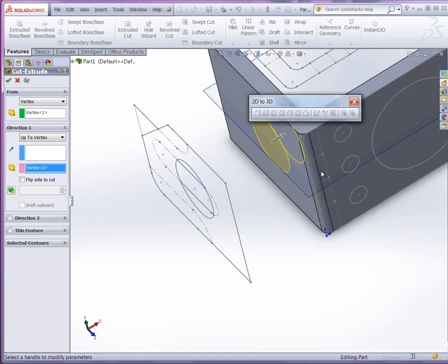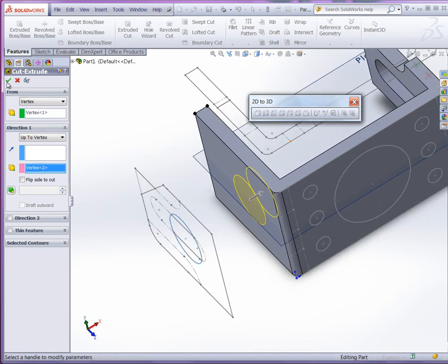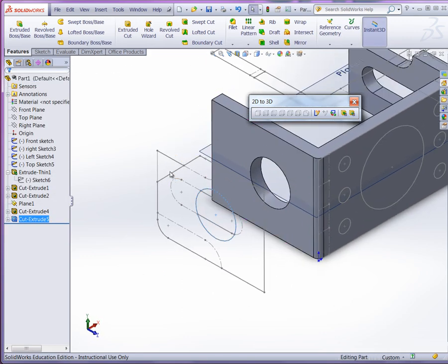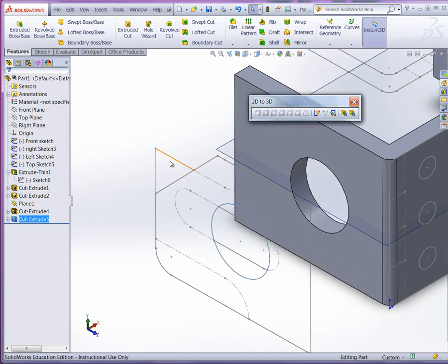Let's select that point there, and that should go through the face, and there we should have our hole. Then this edge right here, this is actually a chamfer, okay? But once again, because we don't have a closed profile here, you can either create it by editing the sketch, or since we know what the dimensions are, or we could read the dimensions too, we can select the edge and just simply do our chamfer.